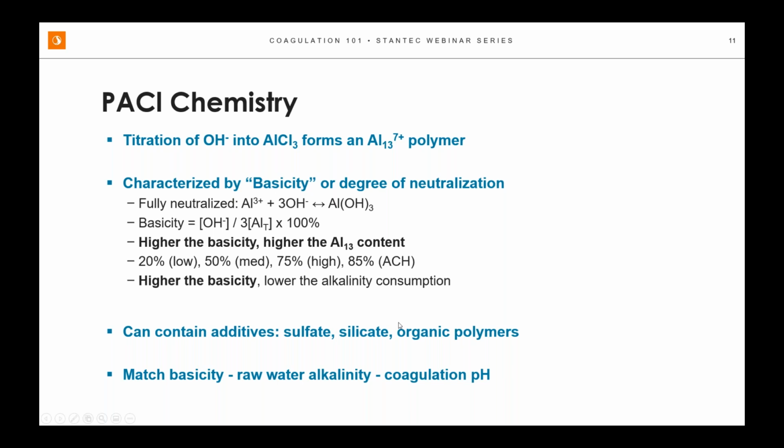However, if you're on the West Coast or someplace like the Colorado River or the North Saskatchewan River, and you've got a lot of alkalinity, you want something that has some acidity so that it can drop the pH into the range in which these coagulants work best. So there's a lot of testing involved, and we'll give some examples of how this works in a bit.